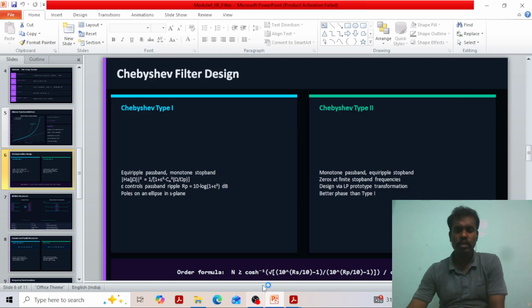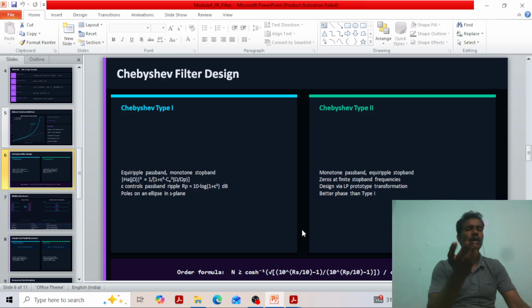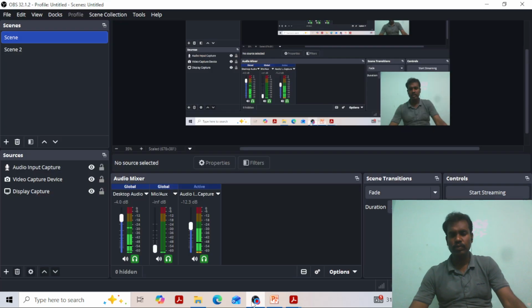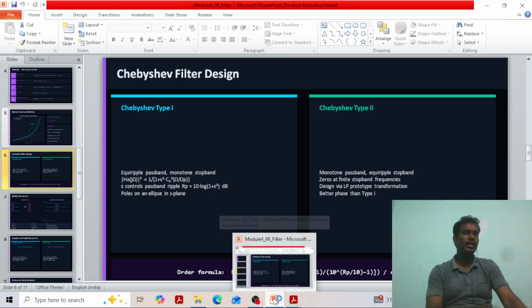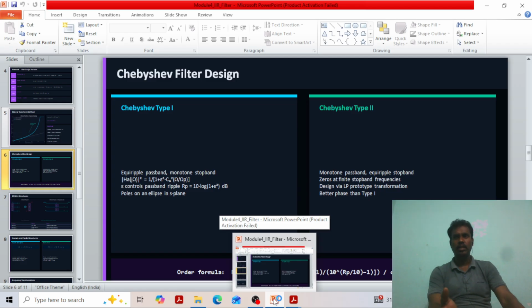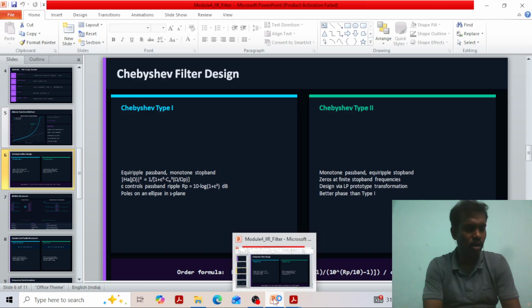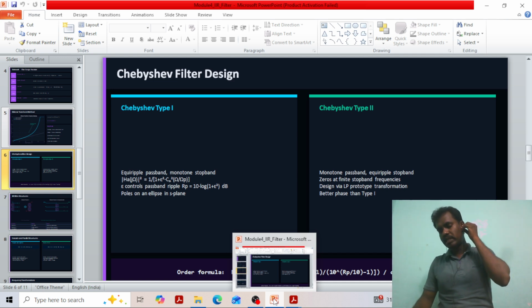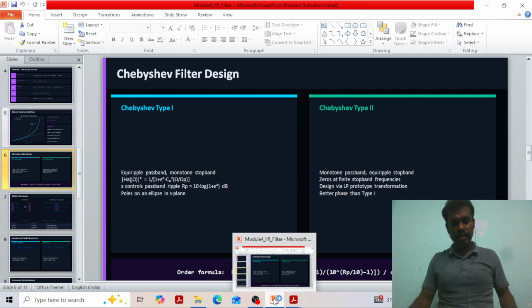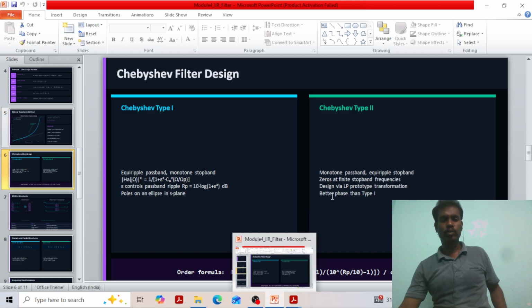Okay. So the transformation of an analog transfer function into a digital transfer function is similar to frequency translation: by substituting the formula into H(s), we can convert low pass to high pass, low pass to band pass, or low pass to band stop. But in analog to digital transfer function conversion, we do not convert the S domain to the S domain; we directly convert the S domain to the Z domain. So the two well-known methods are impulse invariance and bilinear.